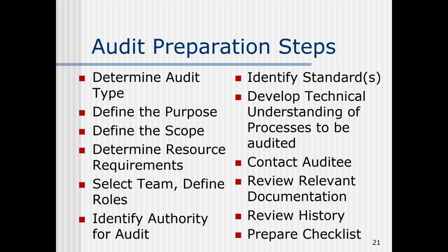But if it's an in-process part, maybe it can't meet specification because there's further machining being done. But is there an in-process measurement that they check? Do the employees verify the work from those previous to them before they start adding more value to this part? Those are all kinds of standard questions you can talk about with any individual process.